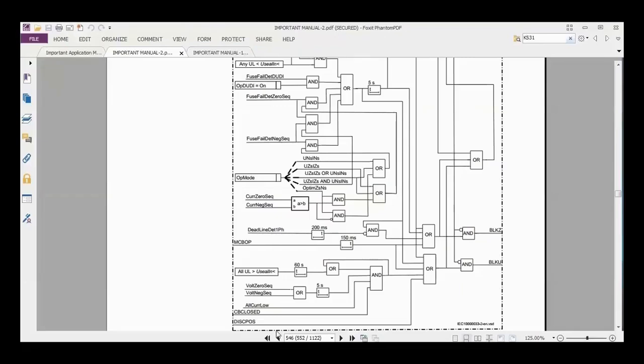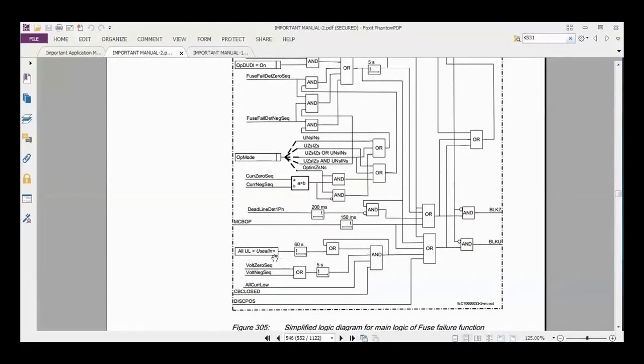Look, sir, if you inject all the voltages for 60 seconds, that's an indication. We said the 2 at the beginning on the left means an indication. If the 2 are drawn at the end, it means a stop indication. If you inject all the voltages correctly and equally with each other, after 60 seconds, if it sees a 0 sequence, and the 0 sequence is present for 5 seconds, it will trigger a block. Meaning, the total time is 65.